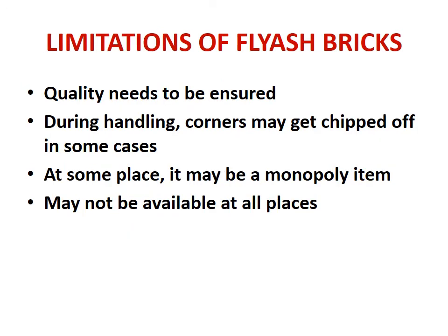Let us see the limitations of fly ash bricks. Quality needs to be ensured. In some of the cases, some problems are observed. During handling, corners may get chipped off in some cases. At some places, it may be a monopoly item, only one manufacturer may be there or may not be even there. Then again, the cost is to be considered with respect to other alternatives available, and this may not be available at all places.